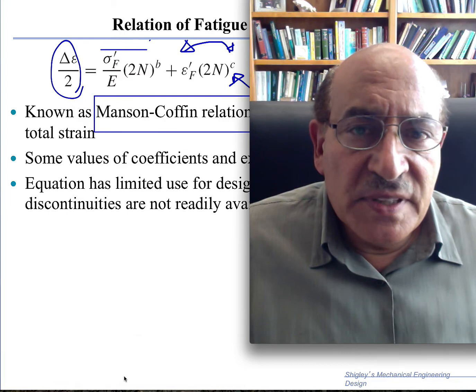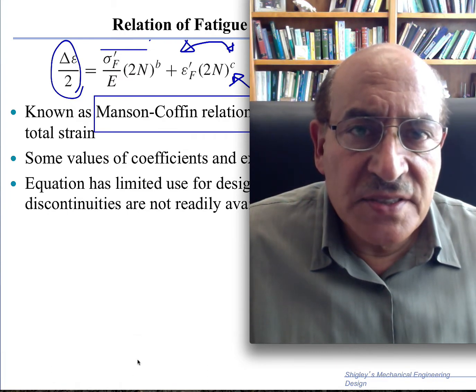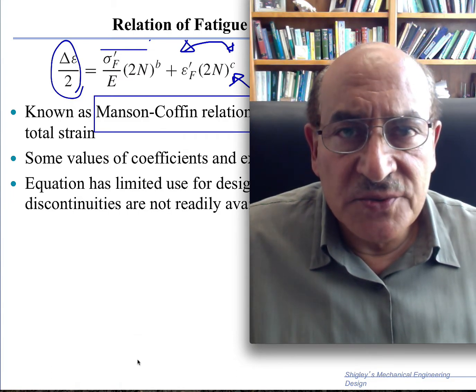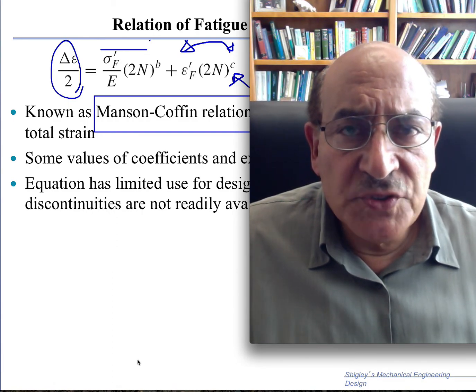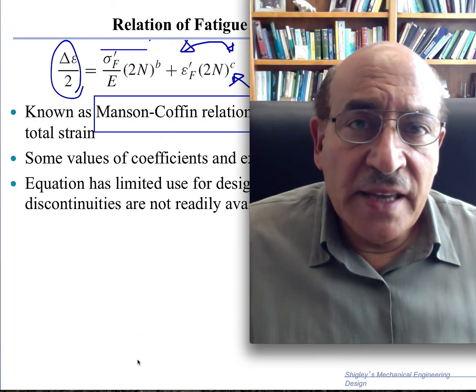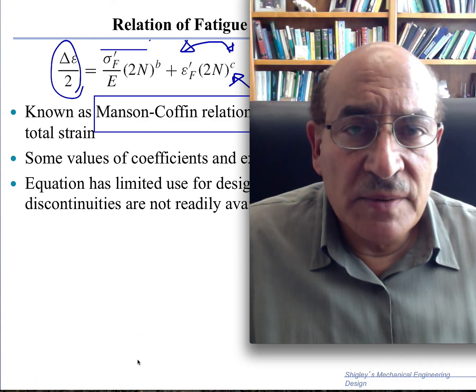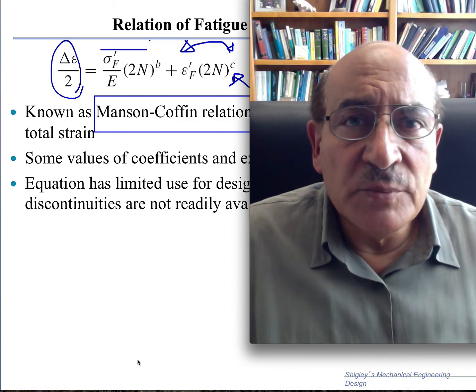Now, the last topic that I wanted to cover today is linear elastic fracture mechanics. We have mentioned that before when it comes to fracture processes: we discussed the idea that we have to compute the stress intensity factor ahead of a crack tip, and then we have to compute the shape factor from given tables or graphs that are provided in design books.